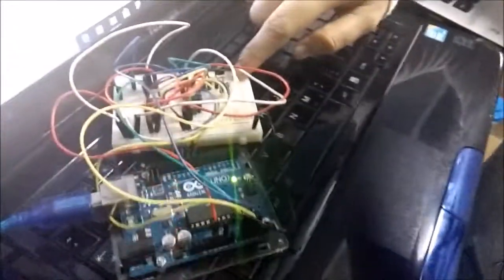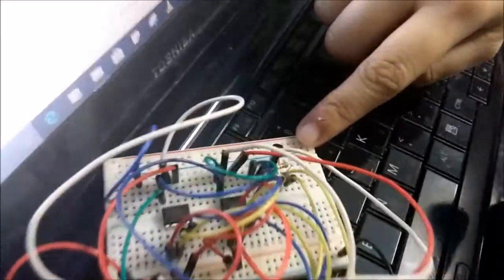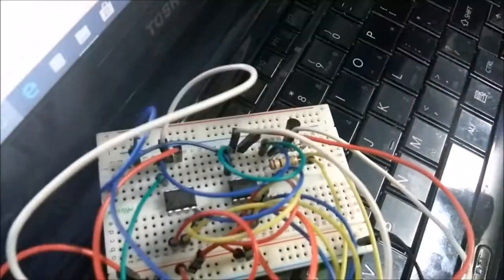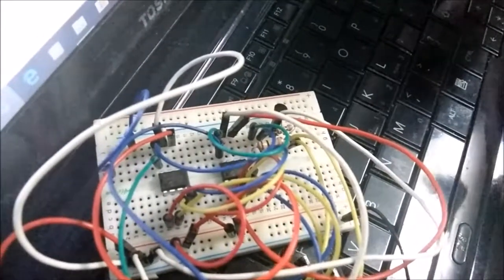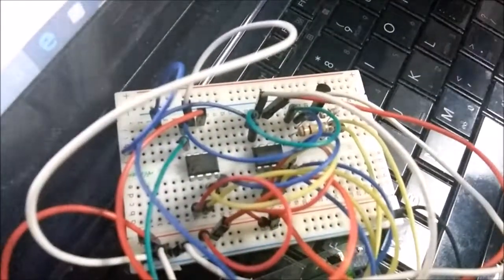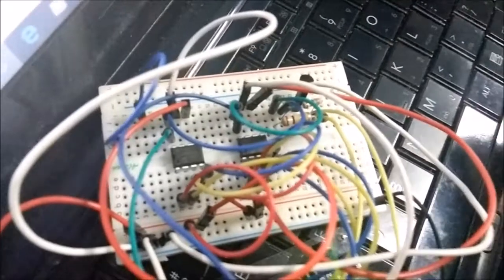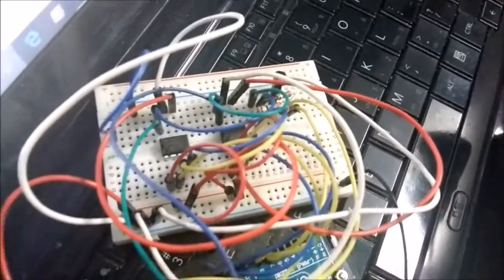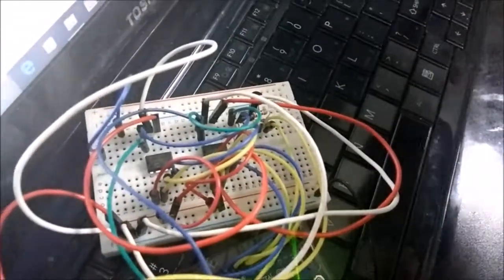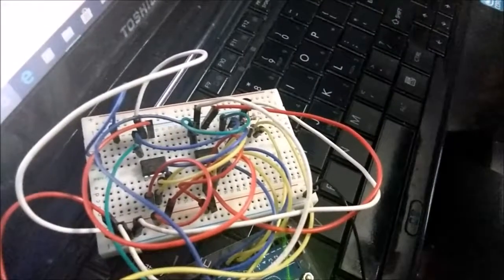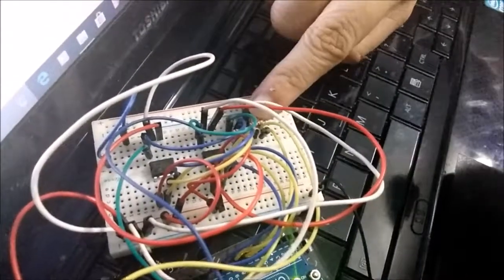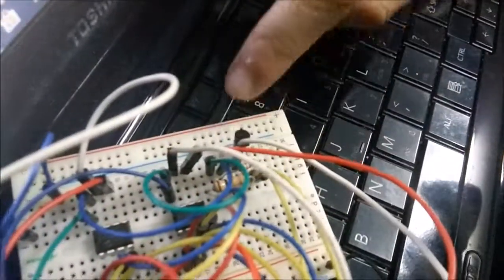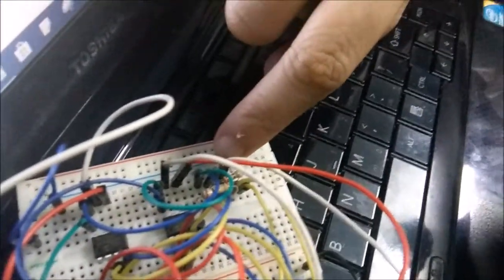This is our circuit, and it is composed of DAC converters, namely the MCP4921, a 12-bit DAC. They are used to sweep the base and collector voltages and provide the output characteristics. A 16-bit word needs to be written to the DAC to set the analog voltage. It is operating in a fixed bias circuit, and we used a 2N3904 transistor.